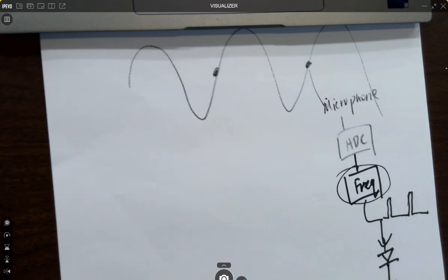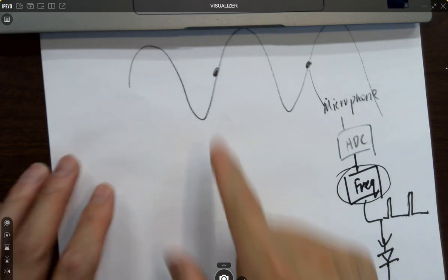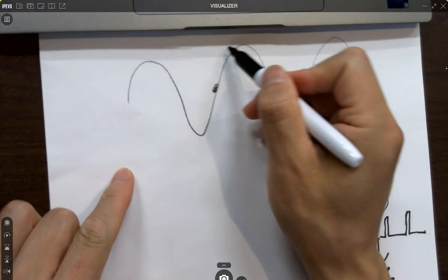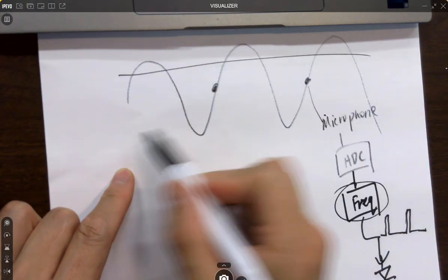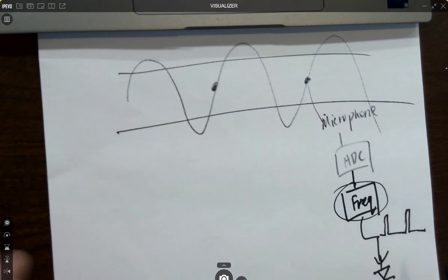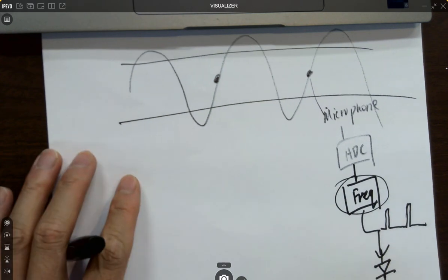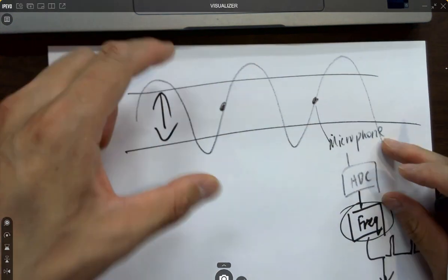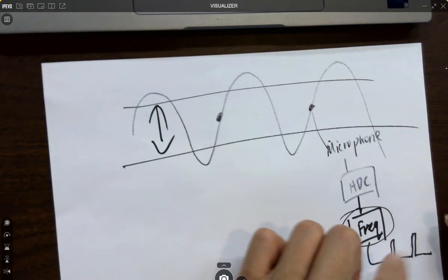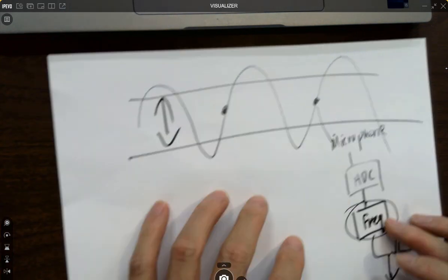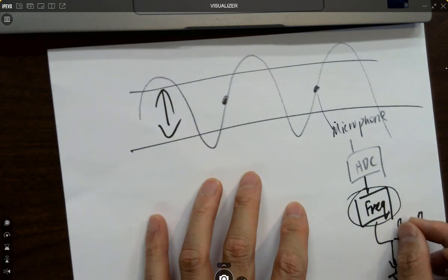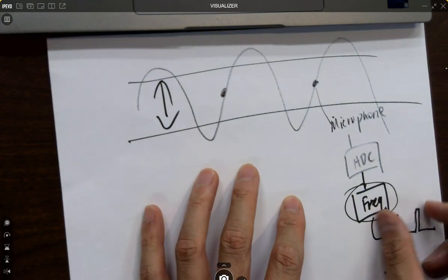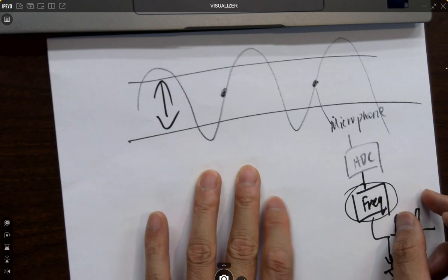You can connect a digital system to anything, right? You can connect the digital system to four little motors, like a switch in the room. Your whistle, all the lights are on. And another way to do that is to see whose whistle can trigger different brightness of the LED. So depending on the amplitude here, right? You have a louder whistle, you get a brighter LED. So you change the duty cycle here, make it wider. Okay. So we take the individual whistle, change the PWM.